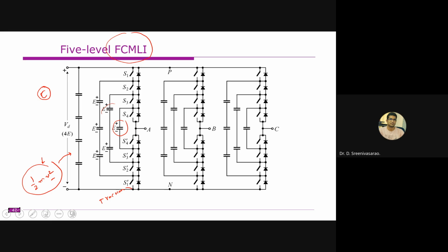Right. So why do we need to do this quickly, right? For example, if this velocity is reduced by half, that means you have already lost 75% of the kinetic energy, right? So that means you must be quick. That is why these capacitors or this ultracapacitor quickly store the energy, and they will gradually release it to other things like batteries or some other places.